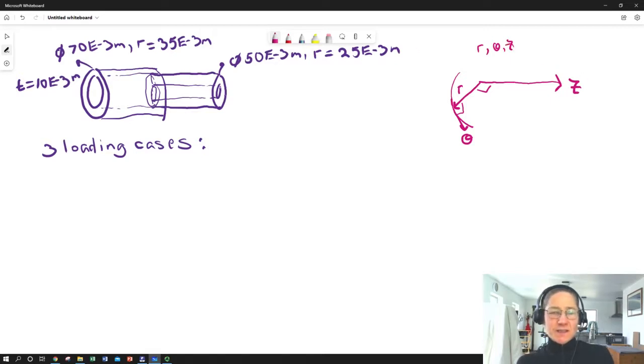So something like this, if we were to grab this cylinder and pull it with a force P, maybe we would be applying that force to the z face, and it would be in the z direction. So it would give us a normal force, zz. If we were to apply torques, we could apply them in multiple different directions. And in fact, this normal force is applied to the end of this cylinder, and when we look at this interfacial area, maybe the two are inserted a little bit more into one another, but we're going to pay a lot of attention to this interfacial area. And in fact, let's break it out and show it as a hoop here. So this is the surface on which these concentric cylinders are touching.